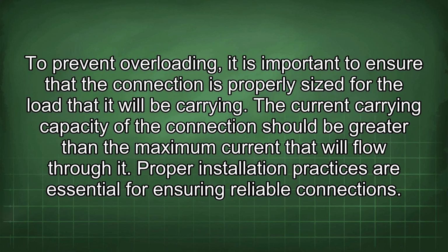To prevent overloading, it is important to ensure that the connection is properly sized for the load that it will be carrying. The current carrying capacity of the connection should be greater than the maximum current that will flow through it. Proper installation practices are essential for ensuring reliable connections.